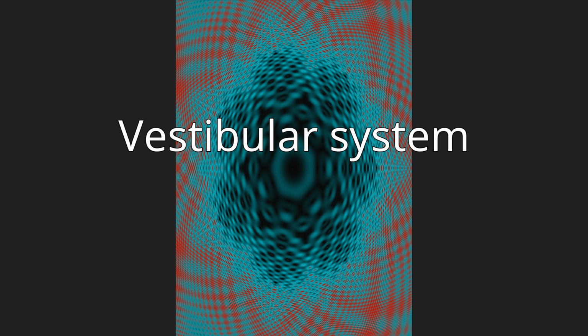Second, if the head experiences sustained accelerations on the order of 10-20 seconds, the hair follicles return to the zero or vertical position, and the brain interprets this as the acceleration ceasing. Additionally, there is a lower acceleration threshold of about 2 degrees per second that the brain cannot perceive. In other words, slow motion below the threshold will not generate vestibular cues.